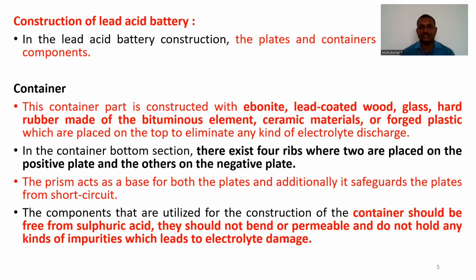The container should be free from sulfuric acid. It should not be bent or permeable, and it should not hold any kind of impurities which lead to electrolyte damage. So great care should be taken in designing the container.